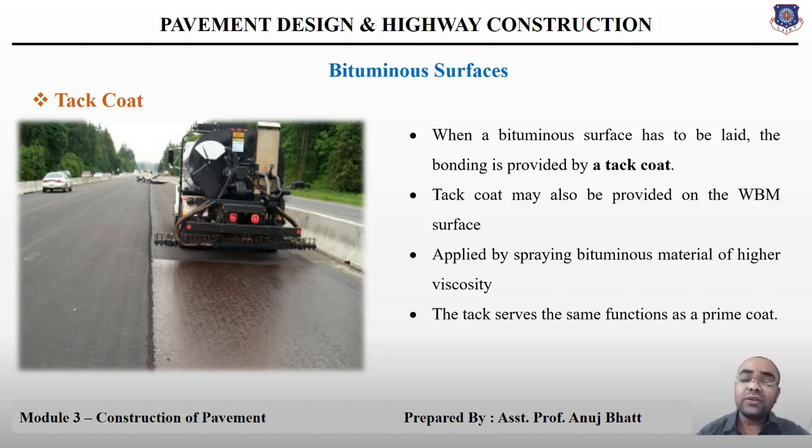For the prime coat, the rate is 7.3 to 14.6 kilogram per 10 meter square area, and for the tack coat, the rate is 4.9 to 9.8 kilogram per 10 meter square area. The functions and the benefits of the prime coat and the tack coat are the same.